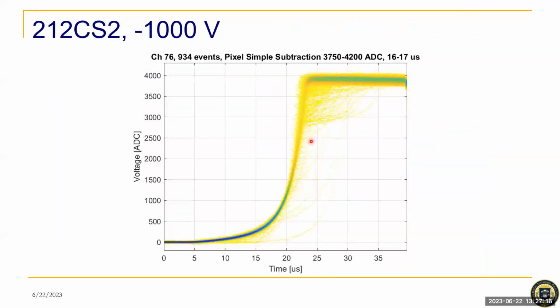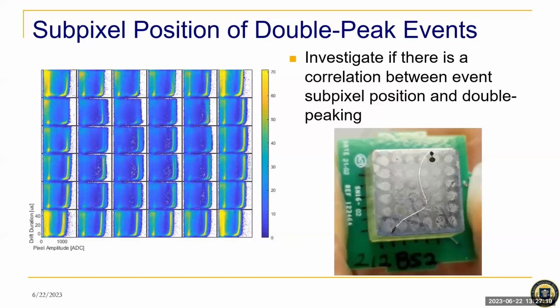Eric, quick question. Sure. I was seeing on the picture of your detector there that it seems like maybe there's a hairline crack in the detector. Is that true? No, that's actually a wire. Okay, good. This black spot is carbon paste. The crystal manufacturer uses a slightly different method to read out the crystal, so they left this wire attached to the crystal, whereas we use a conductive foam. I was just pressing it down against the cathode, and since the wire was also conductive, I was not concerned that it was there. Got it. Thanks. But yeah, short answer is it's a wire. It's not a crack.